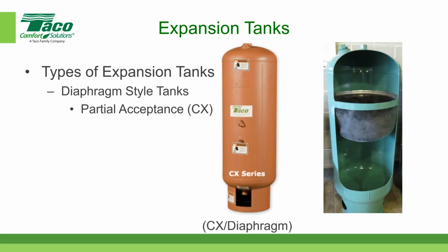Okay, the next category is called a diaphragm style tank. And again, if you look at the photograph on the right, one of the things you may or may not realize is that the water in this case enters the tank at the bottom, and the air enters the tank at the top. And so when the water enters the tank and it expands, it pushes the diaphragm upward.